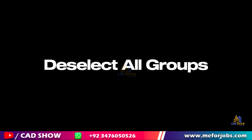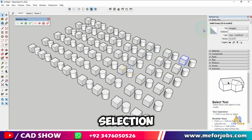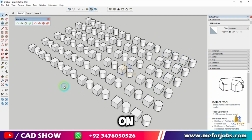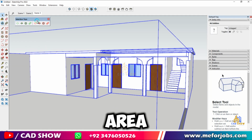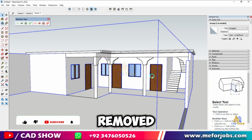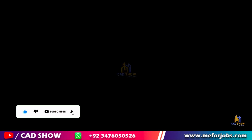Number 7. Deselect All Groups. With the Deselect All Groups in Current Selection tool, you can refine your selection by removing all groups. This makes it easier to focus on individual elements like faces, edges, and components. To use this tool, select the desired area, click on the Deselect All Groups icon, and all groups will be removed from your selection, allowing for more detailed editing of other elements.